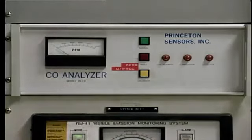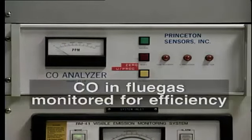The main purpose for monitoring CO in power plant flue gas is more a matter of efficiency than pollution control. The term hydrocarbon refers to unburned components of fuel, particularly oil or gas, such as one may possibly experience from a petroleum refinery or automobile. From the power plant, hydrocarbons are likely to include certain particulate matter, such as unburned carbon or fuel oil smuts.